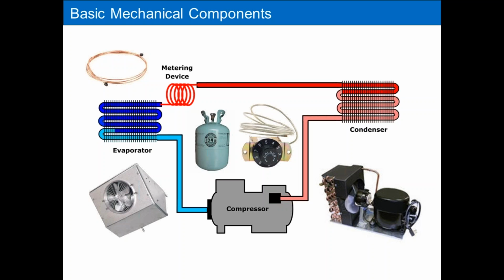And then the refrigerant, for the most part, on medium temperature systems of this nature, you're going to see a lot of R134A systems. If you work on a really old system, original R12 system, you may see some blends out there that have been used to replace the 12 that was originally there, and you may even come across an R12 system that is still in existence. But it's been a while since 12 has been obsoleted, so most of the time it's going to be 134A that you'll be working on.